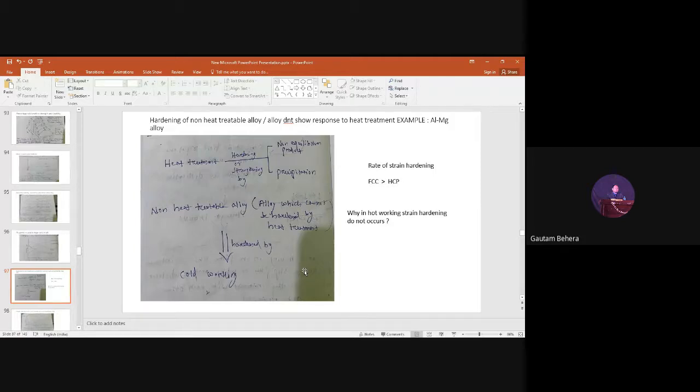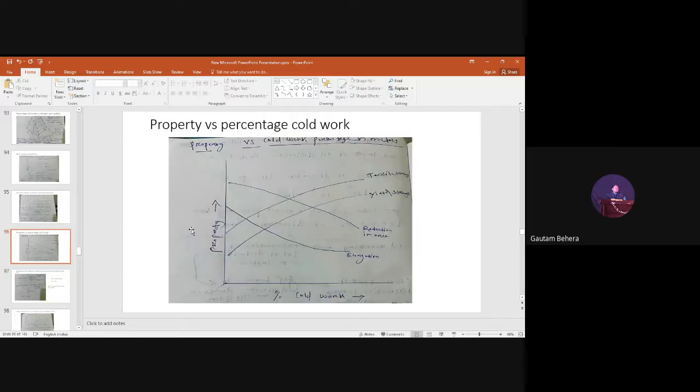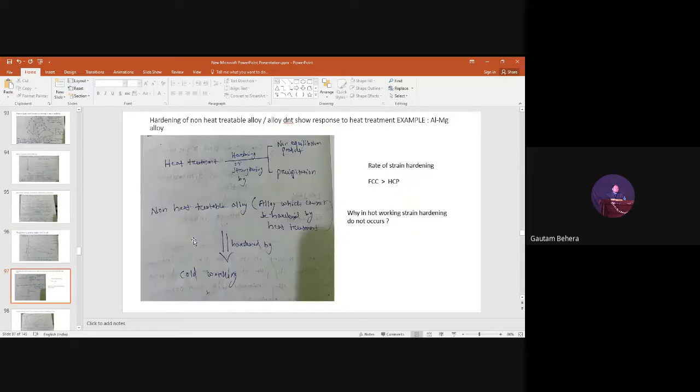So this kind of transformation is a solid state transformation or a liquid to solid state transformation? Solid state, very good. Austenite will transform into either martensite or bainite, right? All are solid phases. And heat treatment itself is a solid state process. You have to remember that. By doing heat treatment on certain alloys, we can have non-equilibrium products like martensite or bainite,